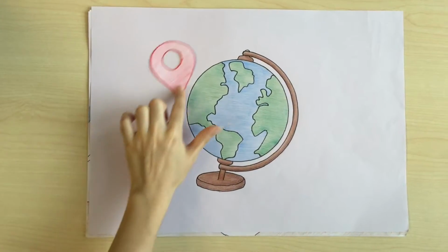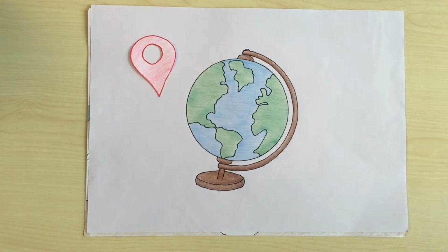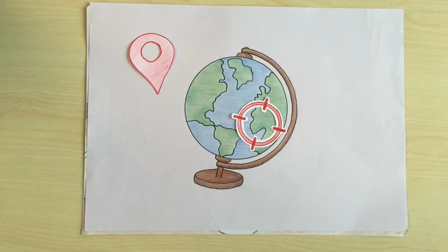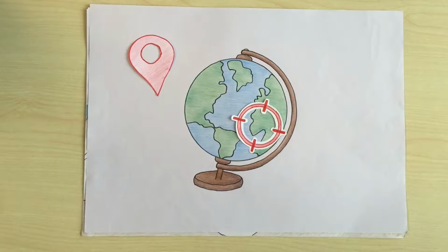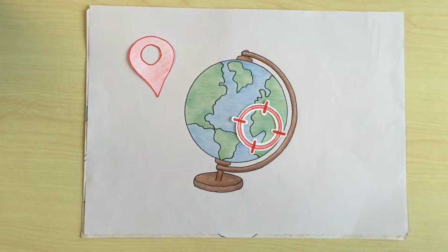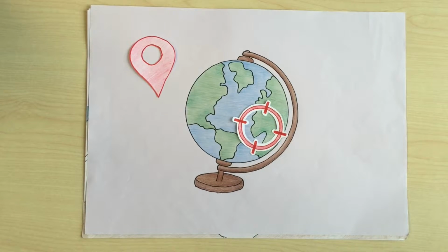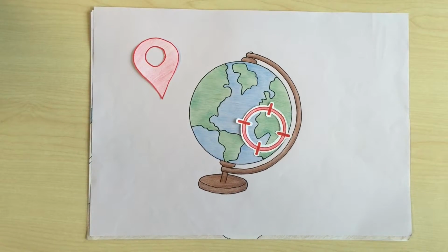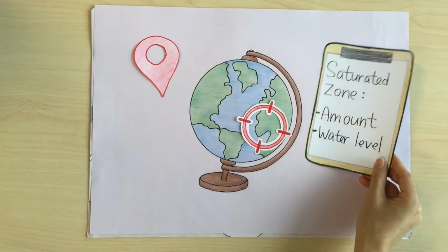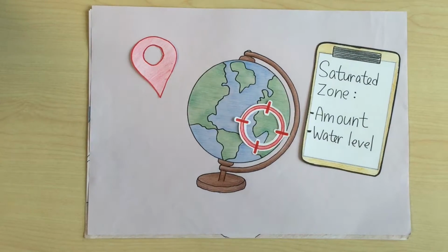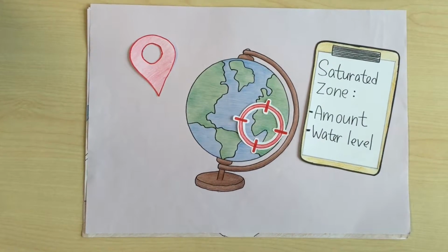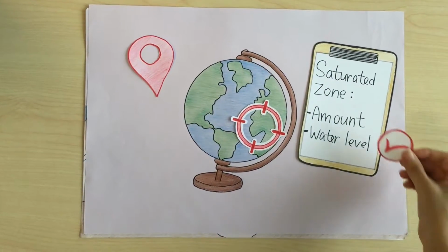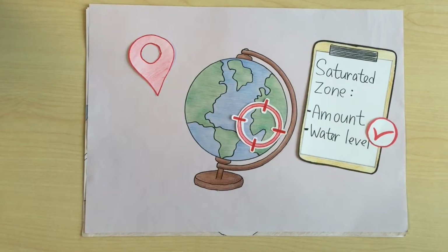To locate a suitable source of groundwater, starting with our hydrologist targets an area, we test and study to identify the hydrologic and geologic features of the area. Second, we use geologic maps and cross-sections to show the distribution of different kinds of rock on the surface and underground. Then, we obtain information on the wells in that area. By doing the test, we can determine the amount of water moving through the zone and the effect of pumping on water levels in the zone.